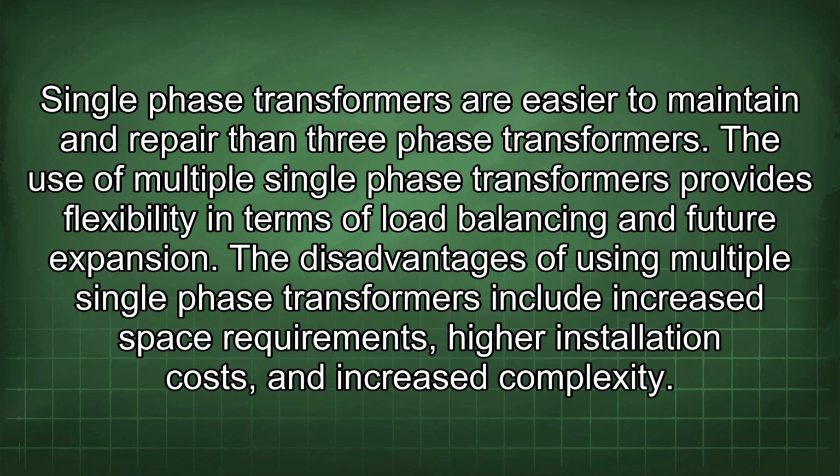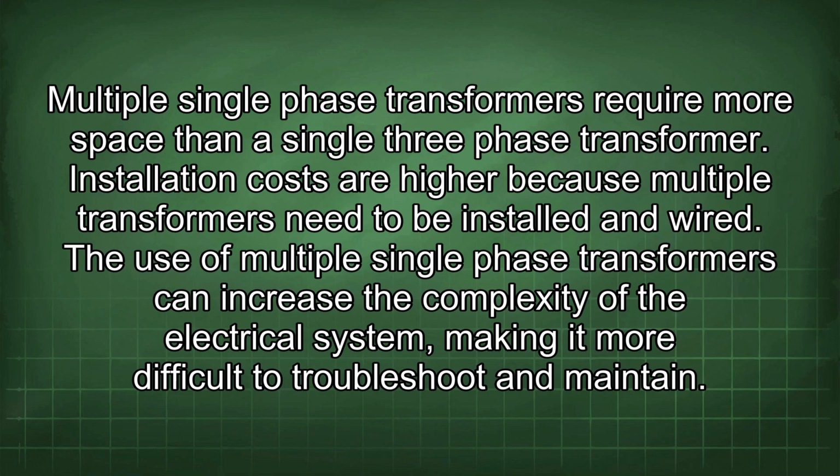The disadvantages of using multiple single-phase transformers include increased space requirements, high installation costs, and increased complexity. Multiple single-phase transformers require more space than a single three-phase transformer. Installation costs are higher because multiple transformers need to be installed and wired. The use of multiple single-phase transformers can increase the complexity of the electrical system, making it more difficult to troubleshoot and maintain.